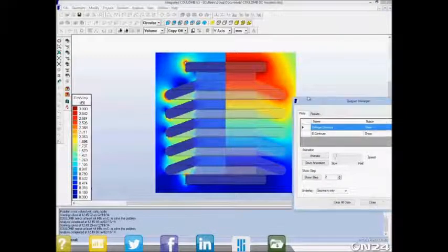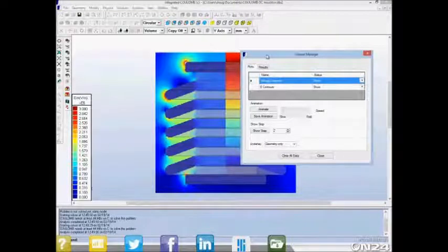So when you're doing a high voltage insulator analysis in any setting, in this case ones you might see along a high voltage line, if you're dealing with DC, you have to realize that there are two answers to the static problem. In this case, the conductivity is set to give a time constant of about an hour. So if you were turning your voltage on and off in a time frame of seconds or minutes, probably the permittivity solution is the only thing you'd be interested in.